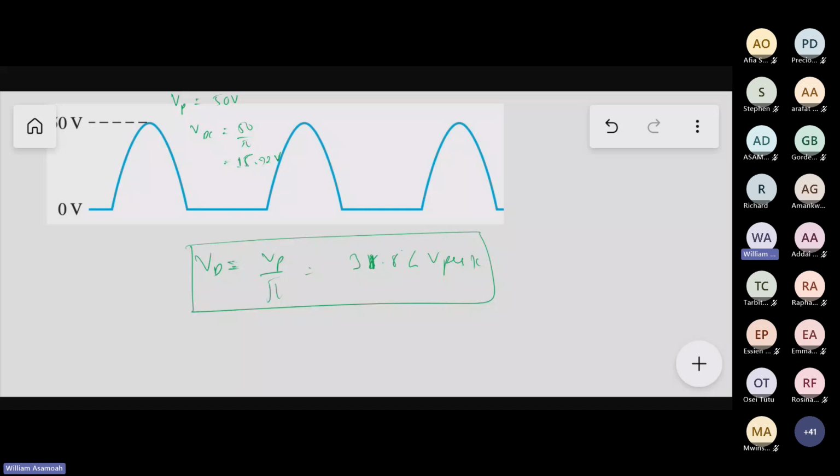We call those ones a signal diode because they can withstand very few voltage. The maximum VBR is 50 volt. Now let's say that you have a diode that has a lesser VBR. Then can you still use it to rectify, or do you need to get a bigger one so that you can rectify? This is one question we face in design problems.